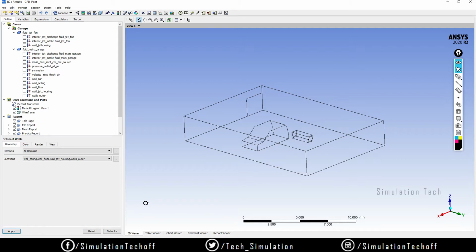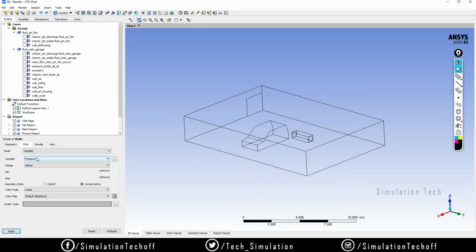Okay, and what are you looking for? I am looking for the temperature changes. So go to the colors option. The colors will show the temperature difference, right? By default it's set to constant, but I want a variable. In the variable selection, by default it's set to pressure. So just drag and drop, and you'll have a variety of options like CO2 mass fraction, density, eddy velocity, and inner wall temperature, like that. I'll choose temperature.